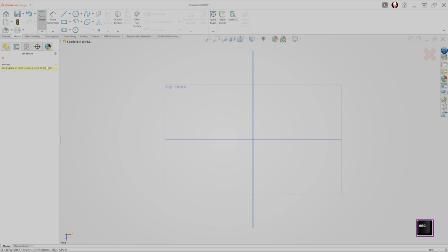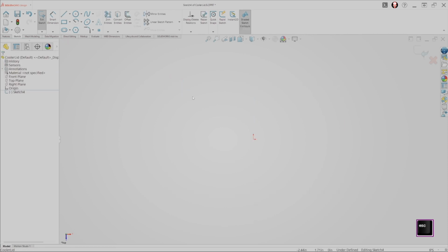Now, I will need to catch back up here for a moment. I will click plane, then top plane, and now I am sketching. I have added and removed a few sketches while explaining this, so mine now says sketch 4, yours probably will just say sketch 1. That's not a big deal, we can just rename it later.